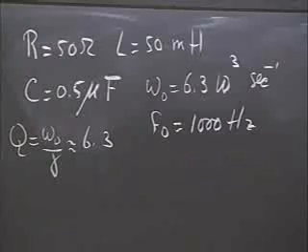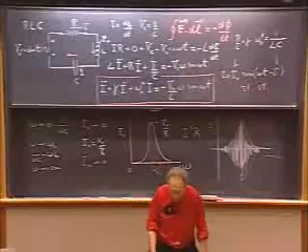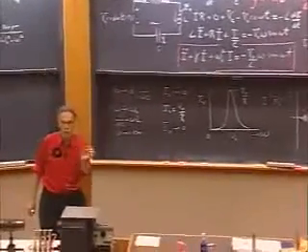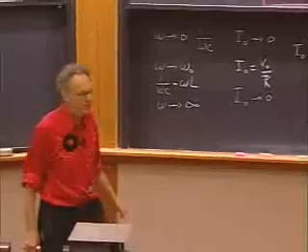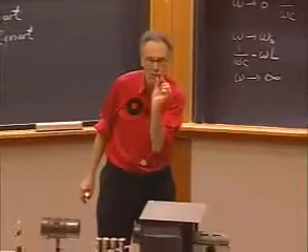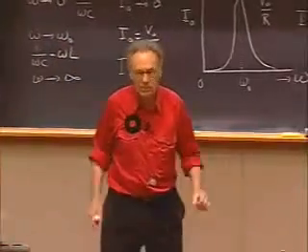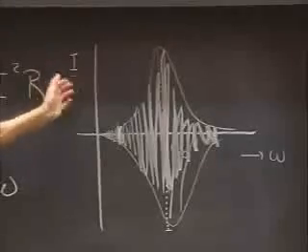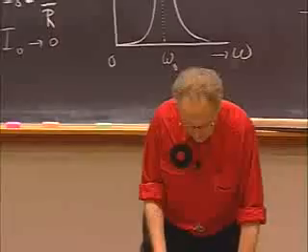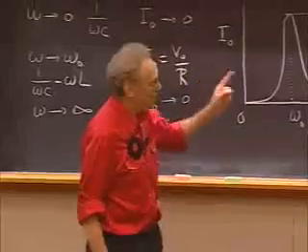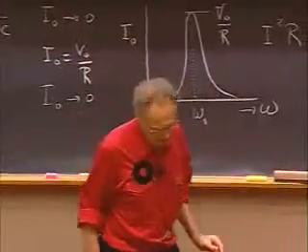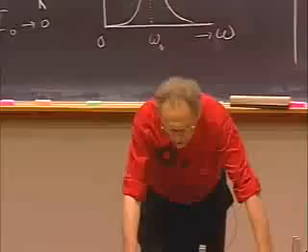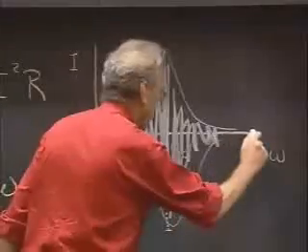And what the V0 is of that circuit is not so important. It is 4 volts, but that's not so important. We measure the potential difference over a very small resistor, which is somewhere in that circuit, 1.7 ohms, I believe. And so that potential difference over that resistor is IR, and R is a constant, and that's what we're going to show you. So we're going to show you something that is directly linear proportional with I. It's not power, it's I. If you want to know power, you have to square it. I squared R is the power. And we're going to sweep it in 1/6 of a second this way and 1/6 of a second back.